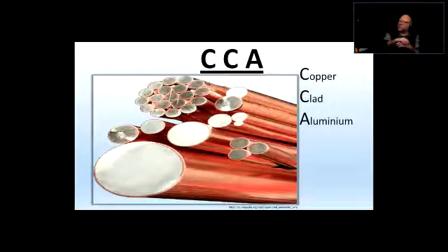They are less expensive, but they do not convey the data as well as the pure copper. So some of the cables that you buy, they're going to be saying that you have to make sure whether you want pure copper wires inside, or do you want the CCA. Right? CCA are less expensive. My personal opinion is, if you have a choice, try to get the pure copper instead of the CCA. The CCA, sometimes you're asking for trouble.